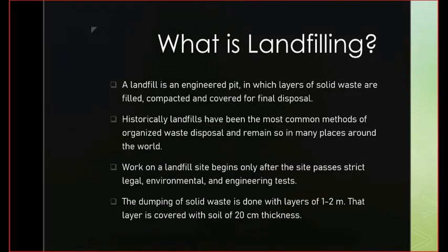So the first question is, what is landfilling? Landfilling is an engineered pit in which layers of solid waste are filled, compacted and covered for final disposal. It's one of the most historical methods of waste disposal, and it remains so to date. Work on a landfilling site begins after the site passes strict legal, environmental and engineering tests. Dumping of solid waste is done in layers of 1 to 2 meters of waste. Then that layer is covered with a layer of soil about 20 centimeters thick.